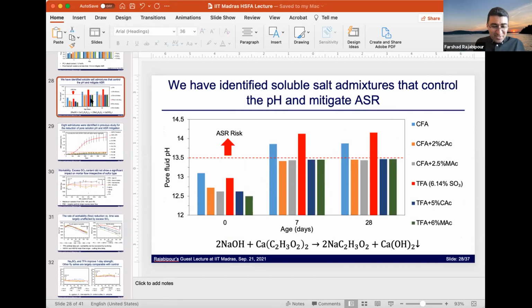That's actually an interesting story. Well, one is the technical need or demand. In the US, and I think in many parts of the world, pozzolans are used as the primary vehicle for ASR mitigation. In North America, there has been a lot of emphasis over the last decade or more on ASR and discovering cases of ASR where in the past there was a belief that there was no ASR.